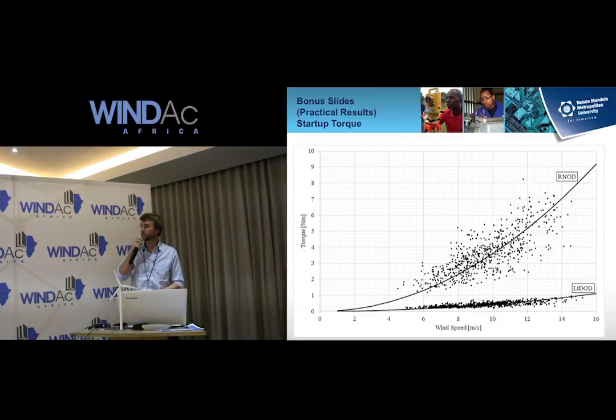So there are the two designs. This is a stationary turbine, and all I'm measuring here is the torque against the wind speed. I've locked the blades. So you can see here 8 times the amount of torque generated from my Reynolds number blades compared to your skinnier lift-to-drag optimized design.